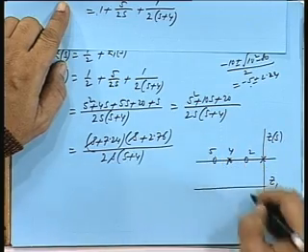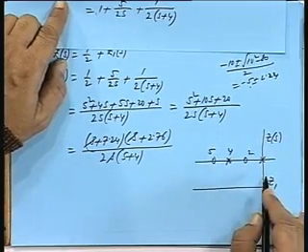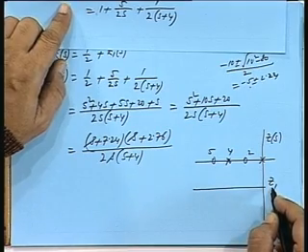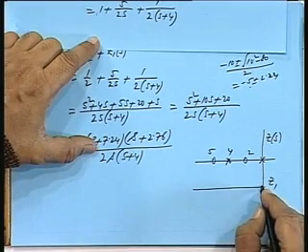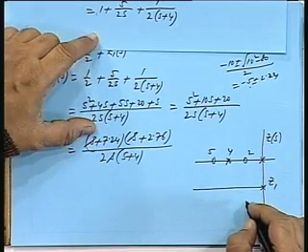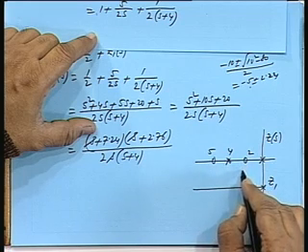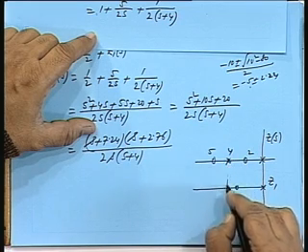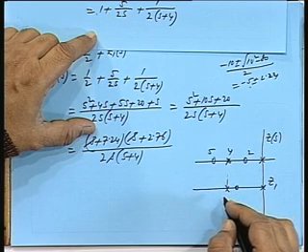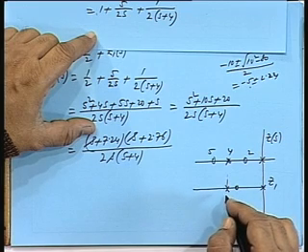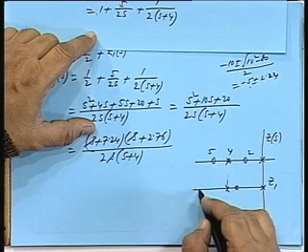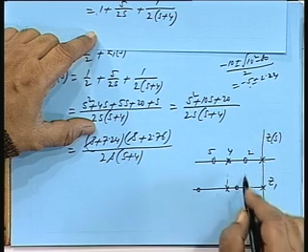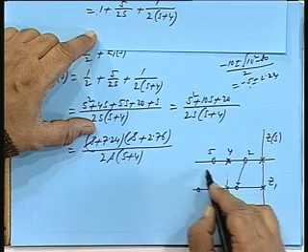I am not drawing the entire sketch, I am just showing the pole zero configuration, and at Z1 now we have got a pole here, a 0 at 2.76 here, pole here, and a 0 at 7.26. You see the shift in the 0 positions.